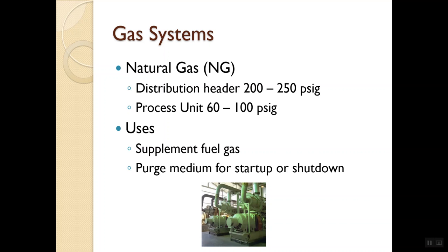And once we get oxygen, a fuel source, and a heat source, we have the prime candidates for having a combustion or an explosion. So if we purge it out with natural gas first, check for leaks, do things like that on startup and shutdown, then we're not introducing air into that already combustible system, a system that already contains combustible materials.